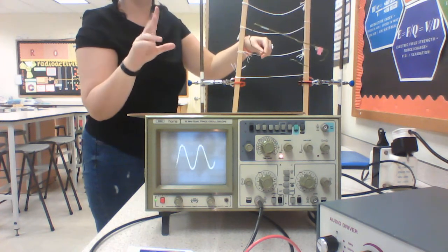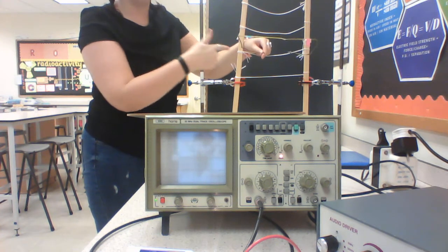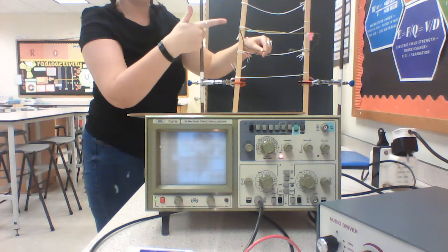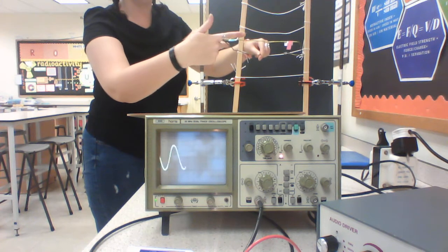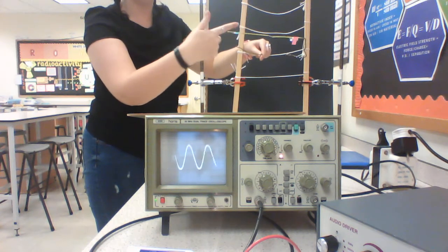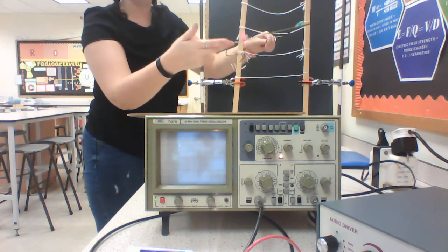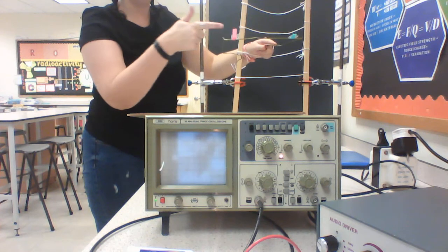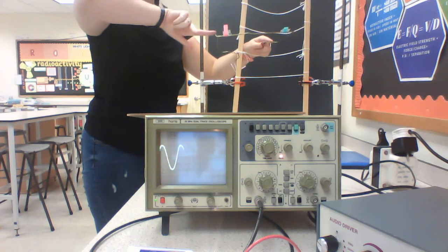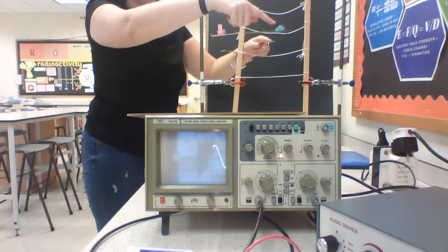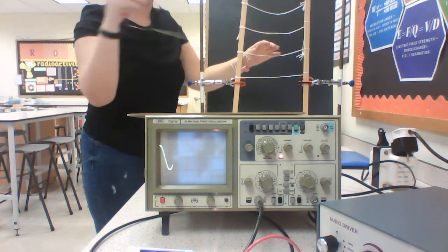If we were to right-hand rule that, so the movement is for the blue, I'm going to move it up. The field, I'm going to say this is the north side of my magnet. My current is pointing towards me, you can't see. So when the blue is in this orientation, current is flowing that way, towards the black. There we go. So there'd be like no current, which is when I get 0. Then here, the blue is now on the other side. Field is still that way, blue is moving down. I've now got current flowing down my blue towards me. So what I've had are the electrons being made go this way, then that way. That's an alternating current. I get it from my AC generator.